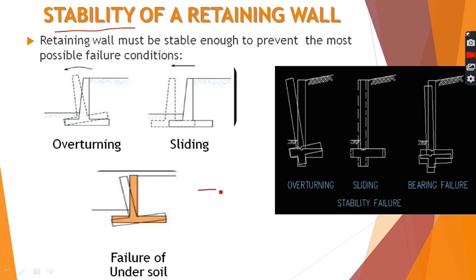For example, when we designed beams, they can fail due to bending. So whenever we designed beams, the bending moment was considered as the primary action. Similarly, when we design columns, they can fail due to axial crushing, so the axial compressive force was the basic force which we used for analyzing or designing the columns.